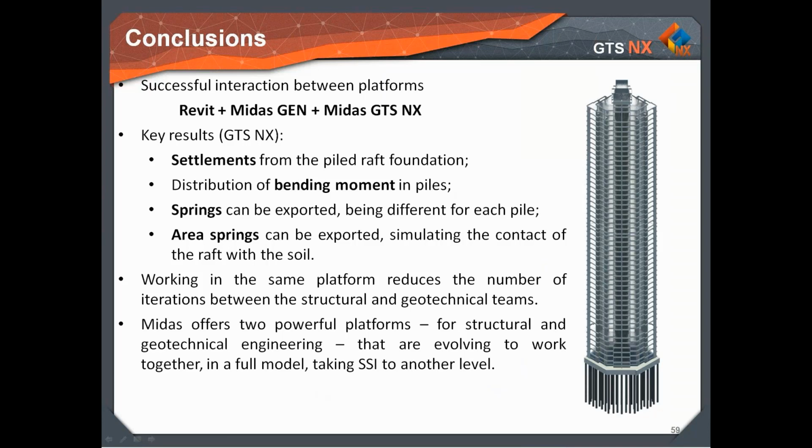Finally, some conclusions. We consider that we had a successful interaction between Revit, MIDAS Gen, and MIDAS GTS NX. The key results from MIDAS GTS NX that we have analyzed are, firstly, the settlement of the piled raft foundation, which might be inside a range of the tolerable settlements for this kind of structure. For interaction with the structural team, springs can be created either for each pile and also as area springs, which are the contact of the raft with the soil.